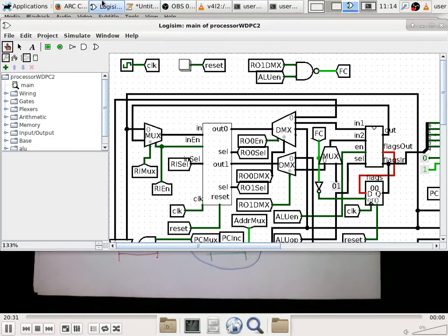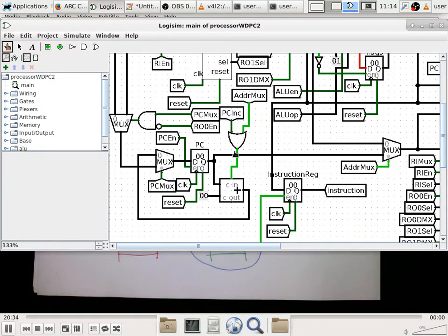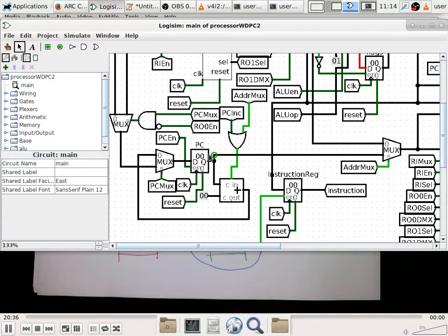So when you look at the processor, the program counter is definitely its own register. It's just that the current way of the toy processor does not have the ability to handle interrupts. Because when you have an interrupt, the processor has to go to a specific location in the microcode ROM that does not actually correspond to an opcode, and it has to execute some code over there to figure out where to continue execution.